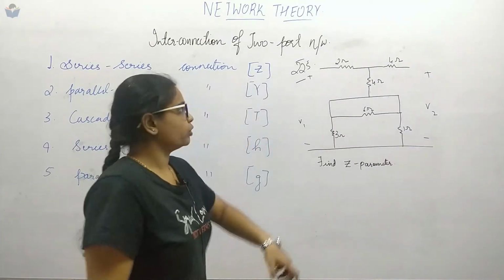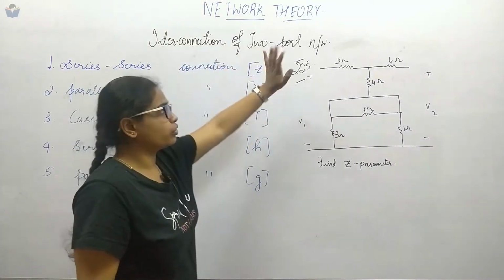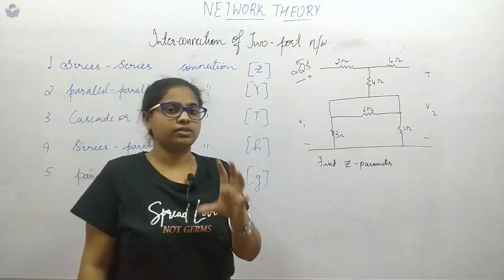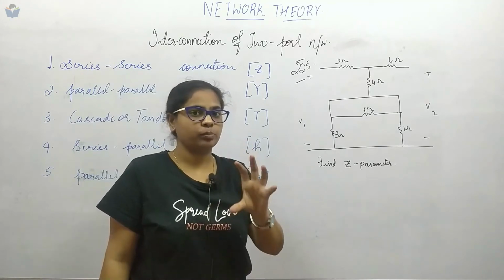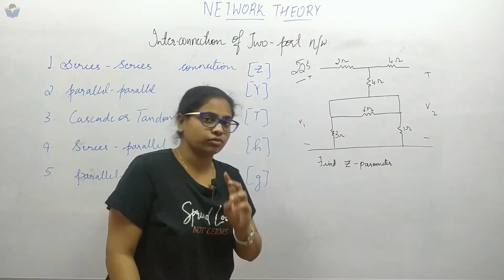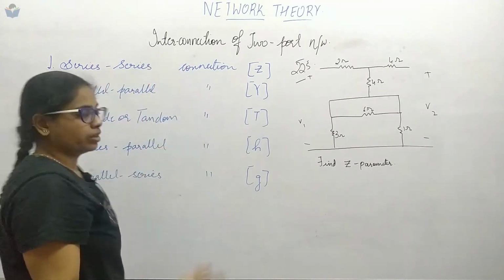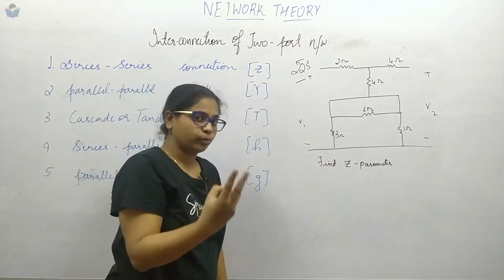So in this lecture, what we will see is the interconnection of two-port networks. That means till now, whatever we have seen was only with the circuit of one-port network, just one circuit of the two-port network. Here, interconnection means there will be two circuits of two-port given.